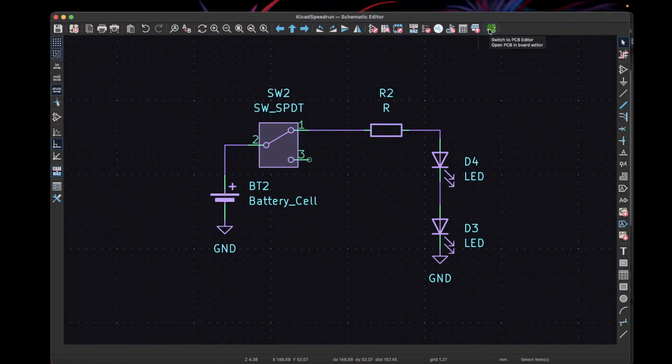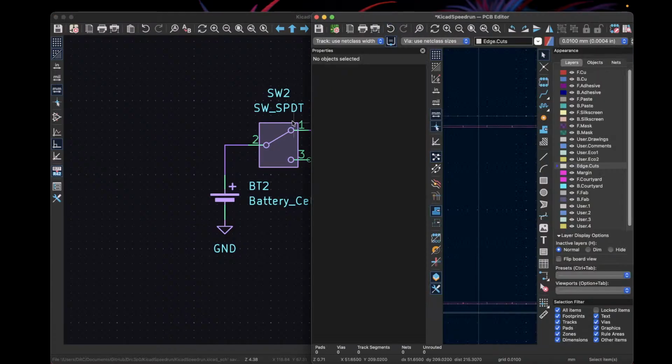What view is this if not the PCB? So this is the schematic view, and this is the drawing of what we want to have wired up. We've assigned footprints to these parts, but this is just the symbols that represent what we're working with. So then we see the ground and everything properly. Yeah, so now whenever we click on this symbol here, we'll switch over to the PCB editor.